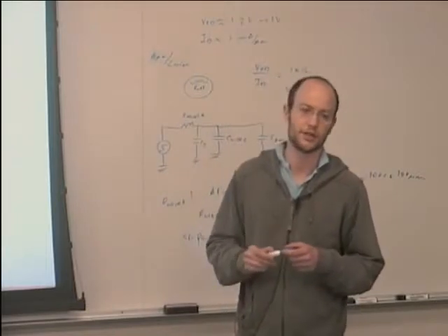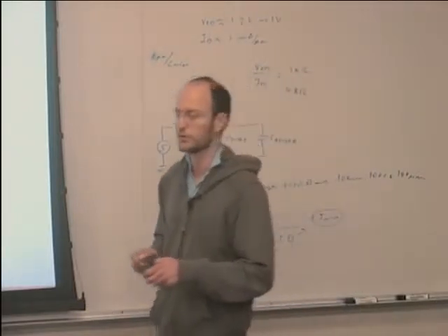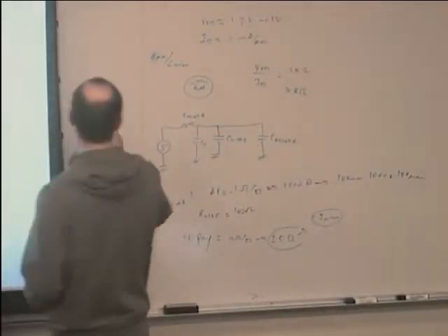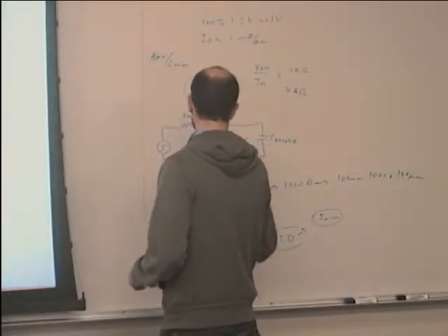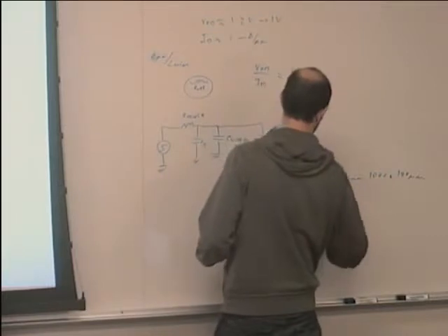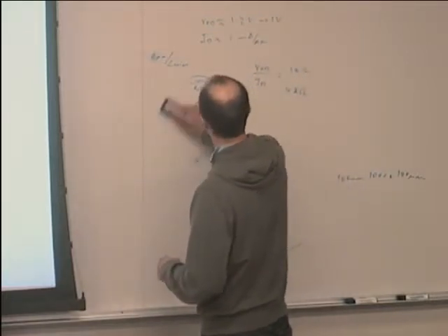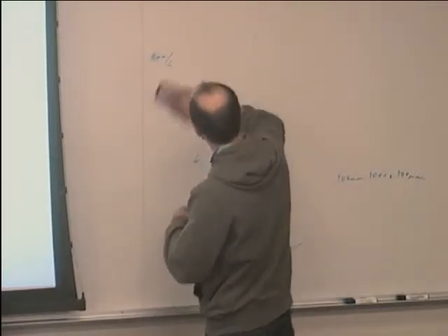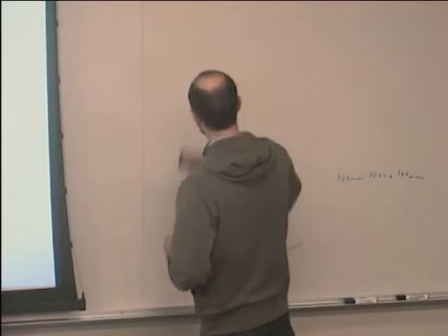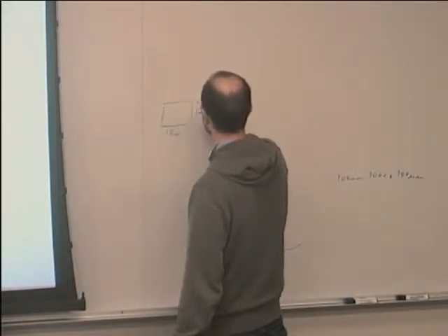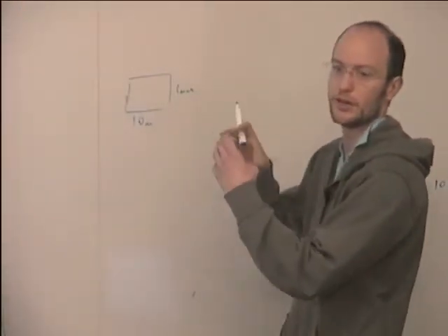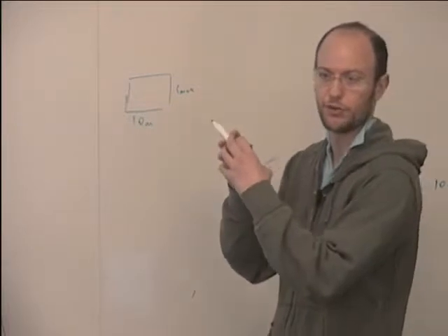So you're talking that, for example, if you have gates, for metal we're talking about 100 microns. A gate will be, again, of the order of like 10 microns by 4 microns. This will be the area of one typical flip-flop, for example.